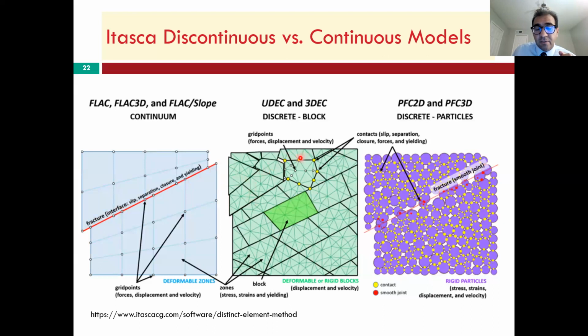However, if we have a system that has abundant fractures, propagation of fractures and joints, then it's going to be very difficult to develop that kind of system in a program that is originally developed to simulate a continuum medium. So it's better to use a tool that is focused on discontinuum modeling. Again, that example of a professional camera for taking professional photos compared to a cell phone. If you have a system full of fractures or joints, it's better to utilize a tool specifically developed for that purpose instead of a tool that is mainly used for continuum modeling but has some options for fractures as well, though very limited and for just specific cases.